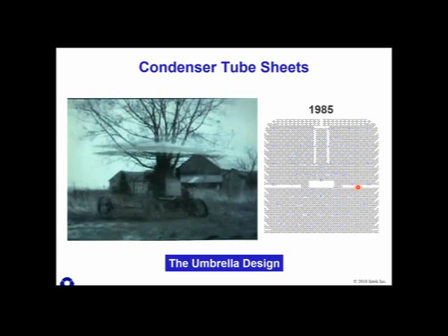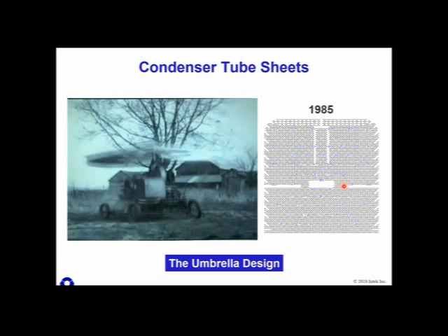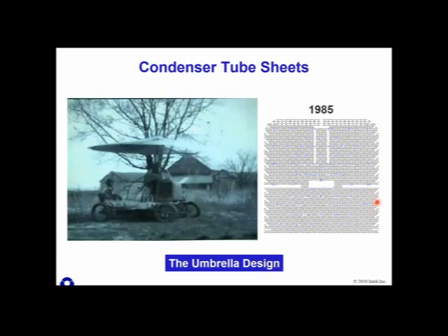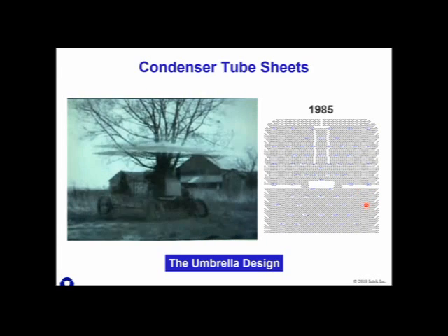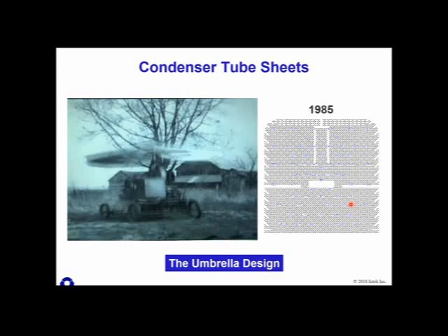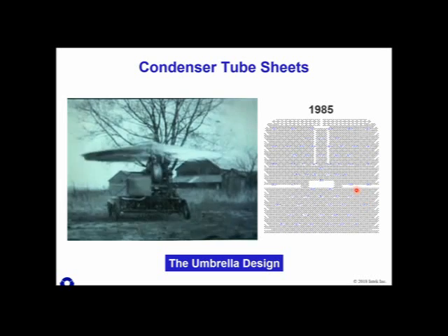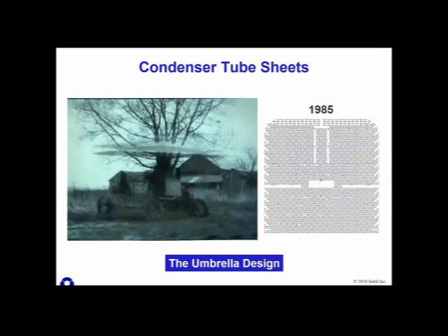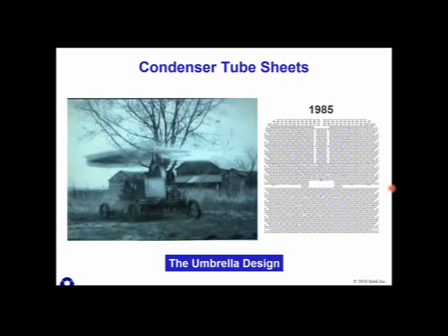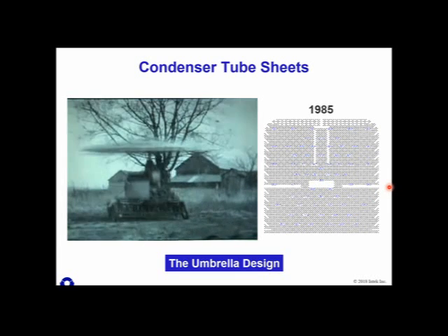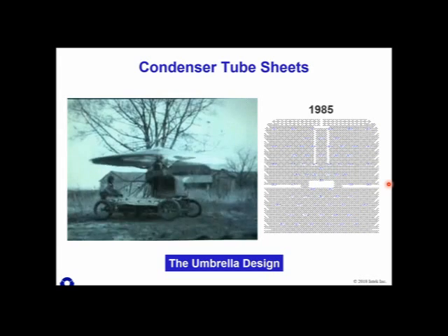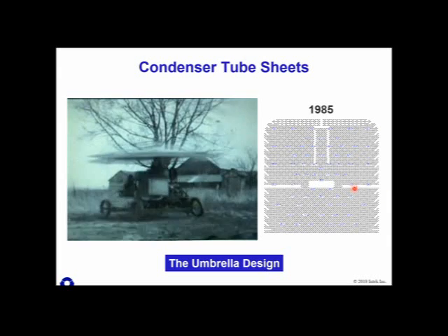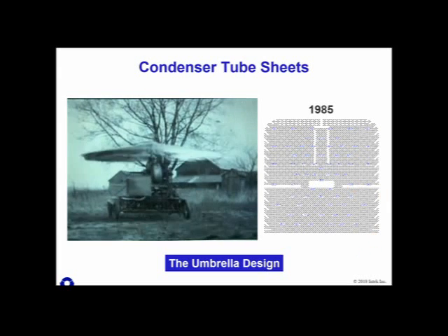So in here, there would be a horizontal plate that catches the falling condensate and drains it out to the side. And so that's done for 2 reasons. In an attempt to remove the condensate loading off of these tubes so they condense steam more efficiently, as well as pulling the condensate off into this low partial pressure, high temperature steam area where the condensate can be de-aerated, so that the dissolved gases can come out. And so that's the 2 reasons for the condensate management there.